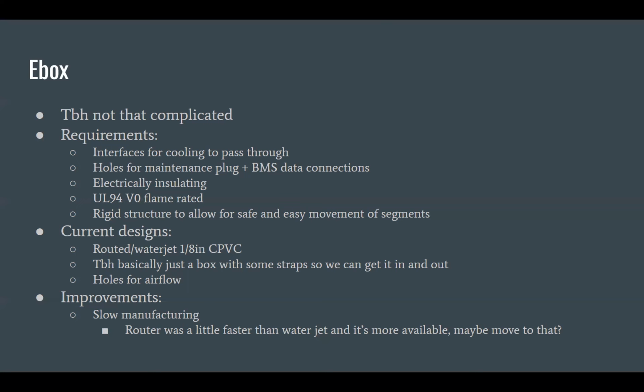You have to take that into consideration in your DXF designs, so you have to basically add toolpath features for these. So it's a little bit more overhead on the design, but it's pretty good. And so it's basically a trade-off: if we have people with bandwidth to do water jetting, the water jetting is great. It lined up poorly this year where the water jet was dying at the time, so we'd only be able to do one. The router ended up being how we did about half of them this year, and the water jet did the other half.